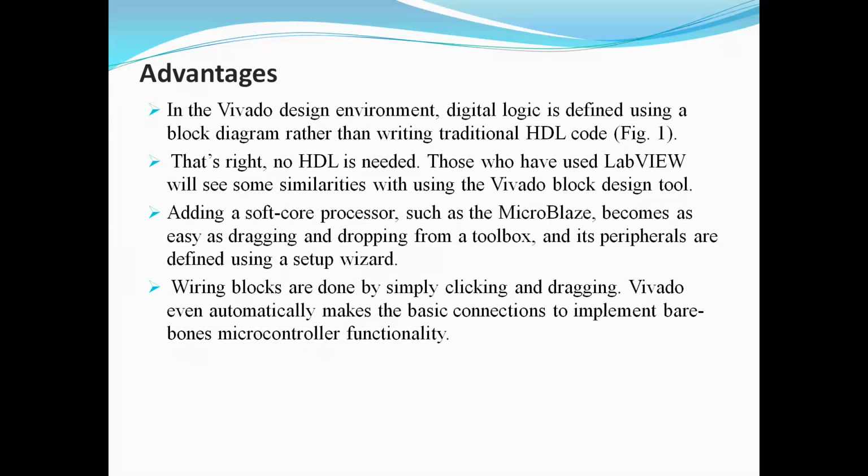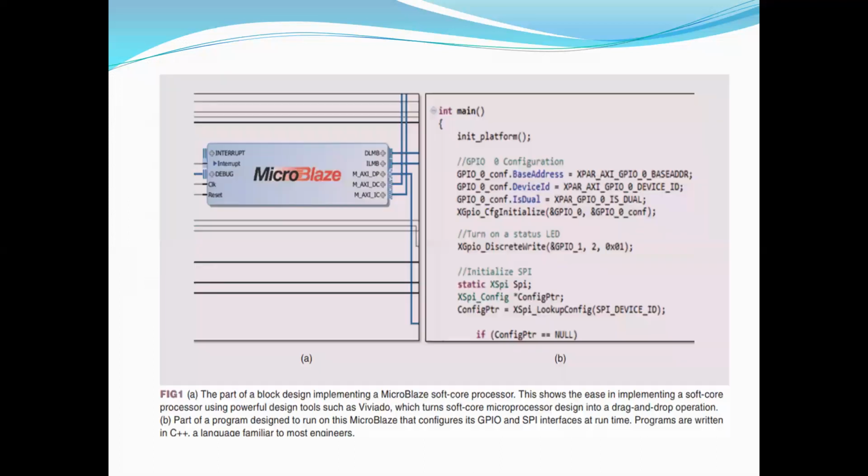Adding a soft core processor such as the MicroBlaze becomes as easy as dragging and dropping from the toolbox, and configuring the design using setup guides. Wiring blocks is done by simply clicking and dragging. Vivado even automatically makes the basic connections to implement bare bones microcontroller functionality.